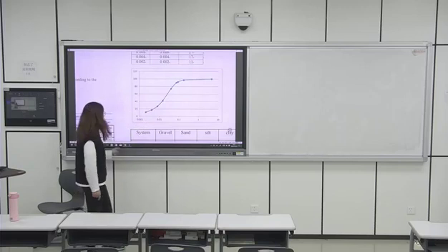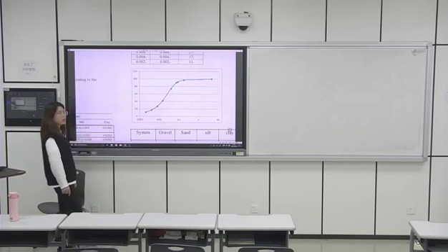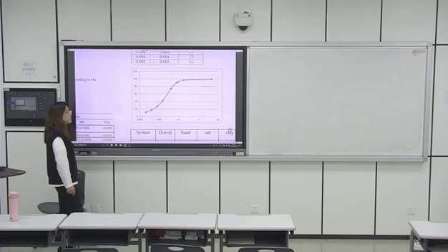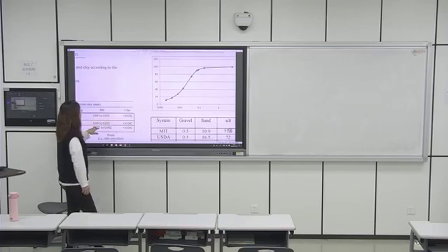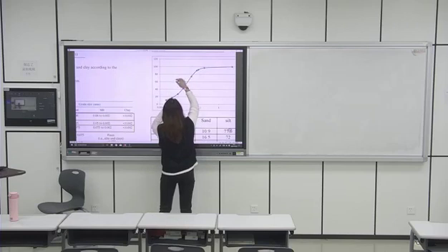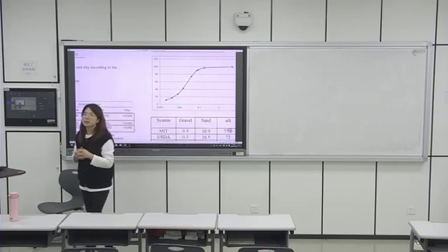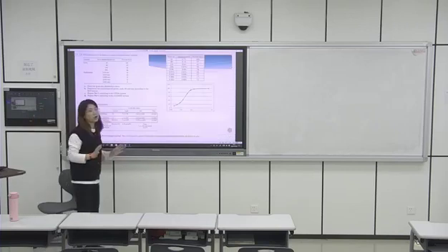That means for clay, which is smaller than 0.002, it is 10%. And then you need to find the silt range for the three systems and find how much percentage is silt, how much is sand, how much is clay, and how much is gravel, that's all.